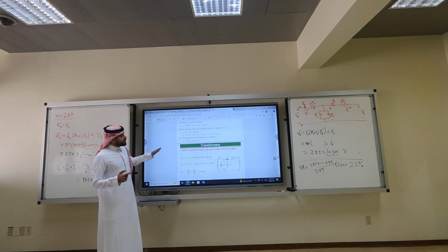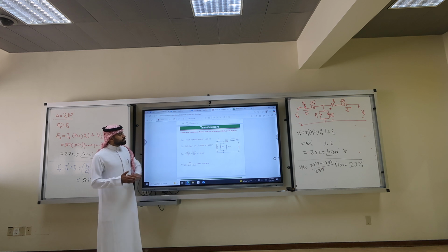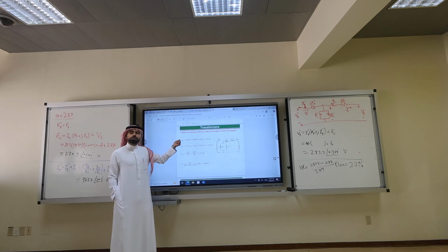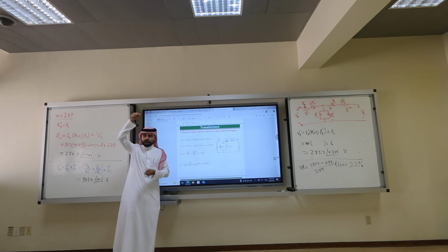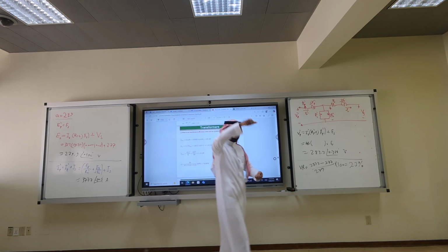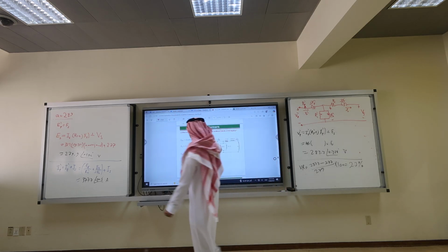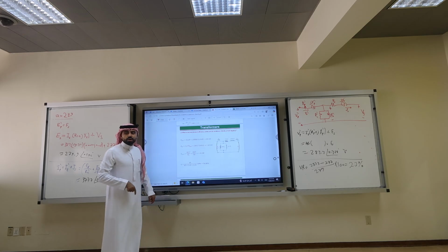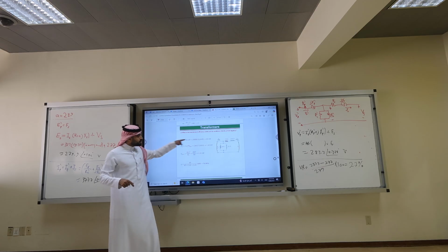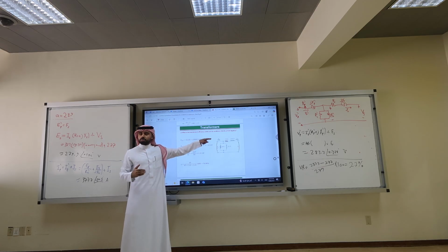To make things easy. It is not only that, let's analyze how he did the efficiency. First of all, he calculated the output power. What is the output power? It is the rated apparent power of the transformer, which propagates all the way to the load, times the power factor. So we are at 85 kilowatt. You can solve the current when we find IS, you can use this and continue. You will get the same IS.